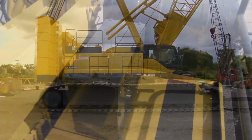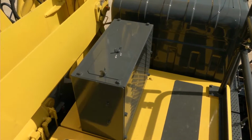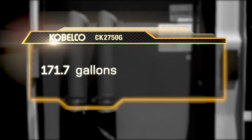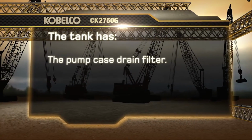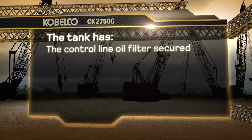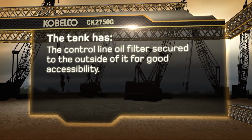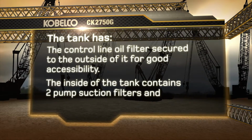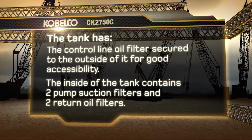Above the fuel tank is the standard air conditioner evaporator. Next is the hydraulic tank with sight glass to visually check the hydraulic oil level and has a capacity of 171.7 gallons. The tank has the pump case drain filter, the free fall brake coolant line filter, and the control line oil filter secured to the outside of it for good accessibility. The inside of the tank contains 2 pump suction filters and 2 return oil filters.